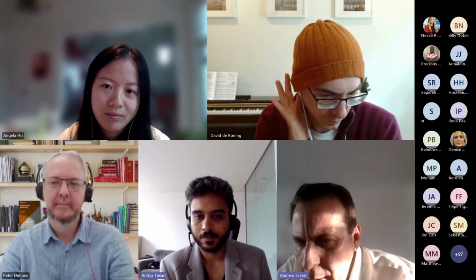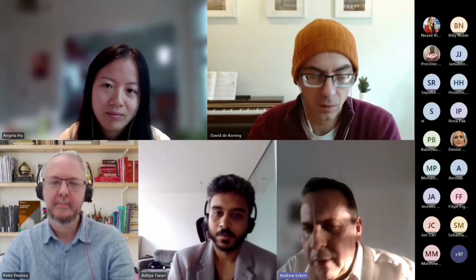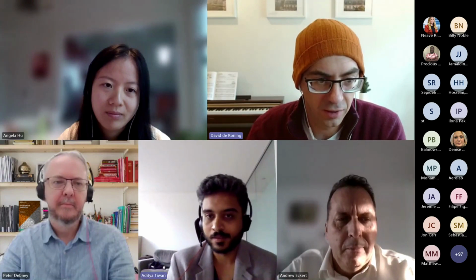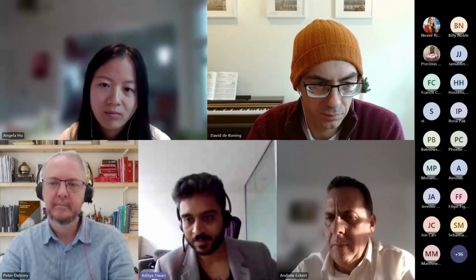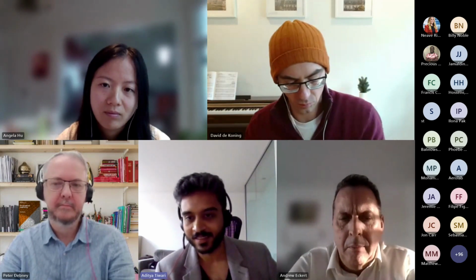Right. Okay. The next question is first complimenting us on the great content in GSA. Thank you for that. So does the substructure extraction from the global model include support stiffness, or does it assume rigid boundary conditions at the section cut? I think that one's for Addy. Yeah, you could do either. It's a short answer. You could apply rigid supports if you want to have fully fixed and pin supports, but if you'd like to have flexibility, the spring supports are also possible. So it's really a modeling choice. But we offer you both, and both are possible with the Grasshopper plugin as well, if that was a question.